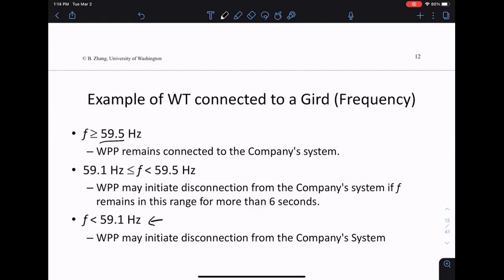So my feeling is going forward, since right now the wind is at this scale, if the frequency is too low, it can just disconnect. So the wind is not really providing a lot of service when there are big outages in the system. In a few years, we may see an update to the code that will require wind to stay connected at a lower frequency.